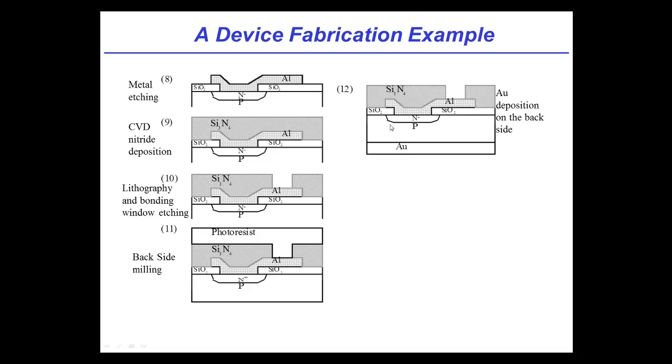And then, so that you have access to the backside of the wafer, you might deposit some metal on the backside. That gives you a good contact to the backside of the wafer. So if you think about it, what do I have now, Michelle? I've got a backside metal, and I have a front side metal with a contact window opening. Well, my guess is now we've got to make electrical connections. I guessed we were going to make an interconnect here, but I had forgotten that the back was oxidized. We had to clean it, and then we had to put a metal to make a good contact.